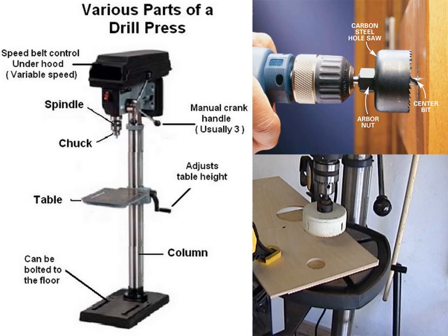Whenever you're using this, you need to make sure that the drill press is secure. They usually do have a heavy weighted base, but it's a good idea to have it either bolted to a table, or, depending on the height of it, maybe bolted to the floor, so that it's not going to tip over while you're using it.